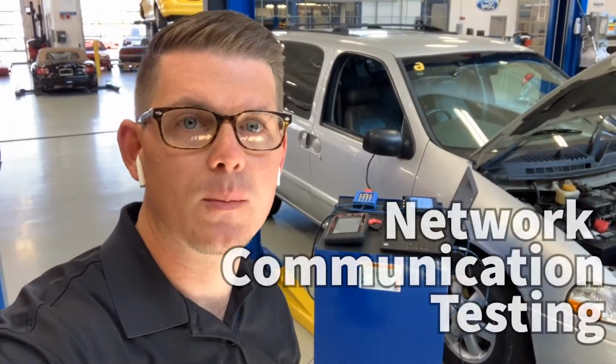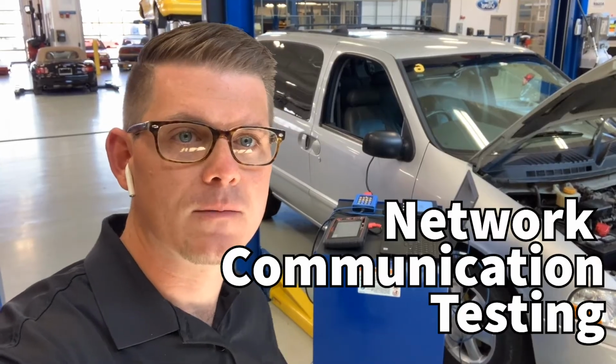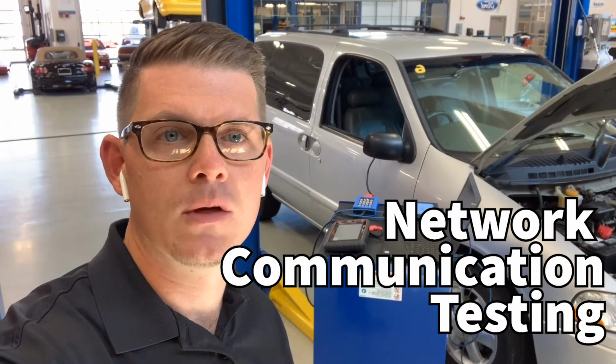Hello everybody. In this video we are going to talk about some network communication testing. I've got a scan tool, a breakout box, and a PicoScope. We'll look at two different types of network communication that are commonplace. This particular Nissan has a K-line serial system for its data, and then we'll look at a CAN system on a newer vehicle as well.